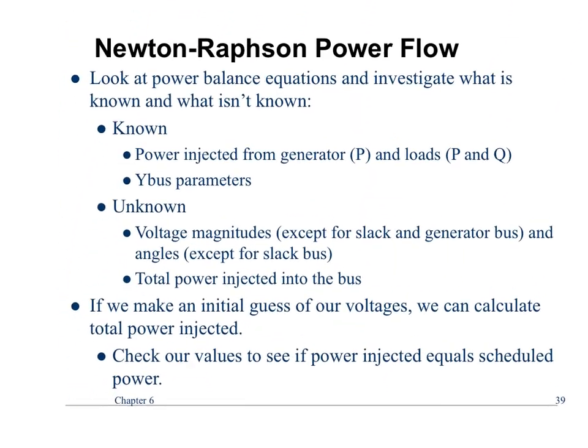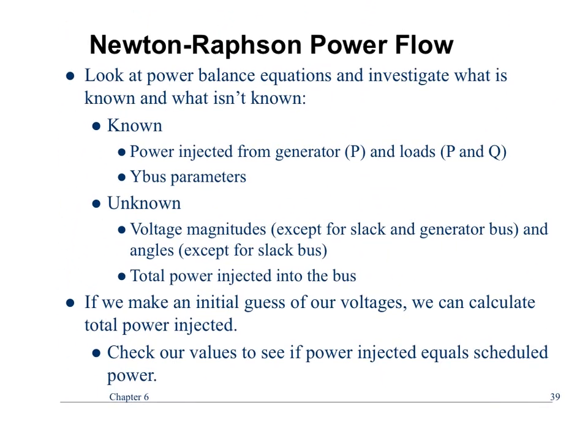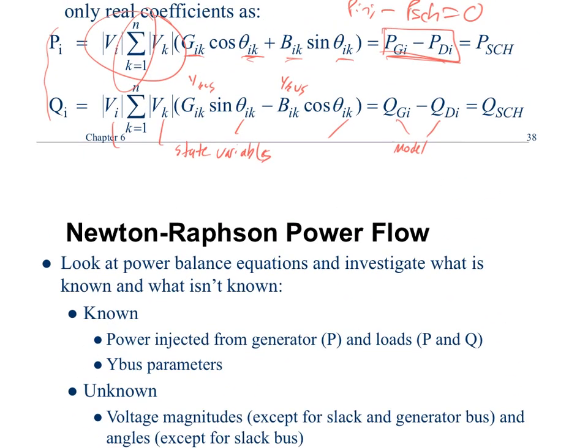And then what would that come from Y bus? Would that just be the model of the system? Y bus will come from the model of the system. No, I know, but G and B, so we create Y bus and just work. Oh, so the question is, where did G and B come from? So remember what Y bus equals. It's going to have some element in here. We'll call it Y11, Y12. Y11 has a real part, G11, plus or minus an imaginary part, B11. So the G and the B come from there.